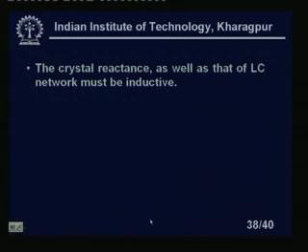Now, the crystal reactance as well as that of the LC network must be inductive, quite obviously. Basically, a piezoelectric crystal, if you look at it from the basic point of view, is nothing but an LC oscillator. We have studied LC oscillators in our analog electronics. It is simply an LC oscillator, the only thing being that L is replaced by the piezoelectric crystal.